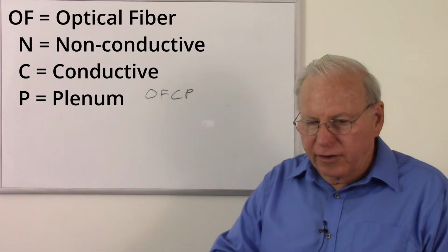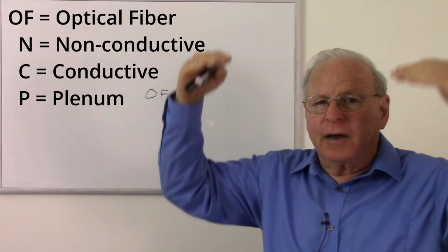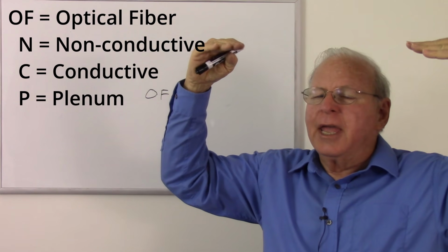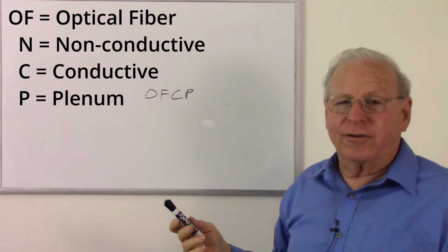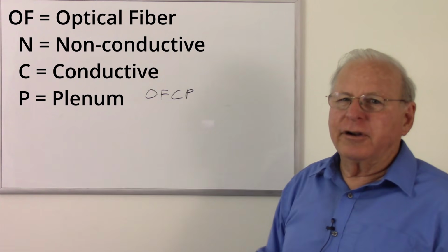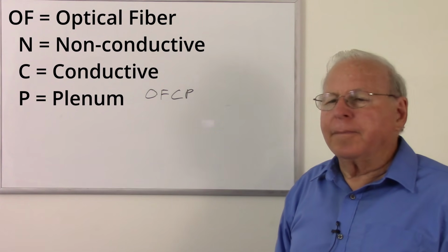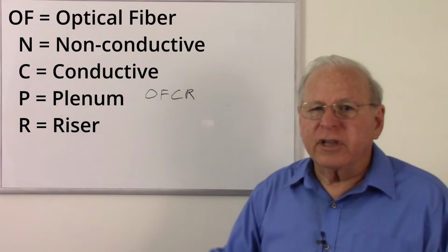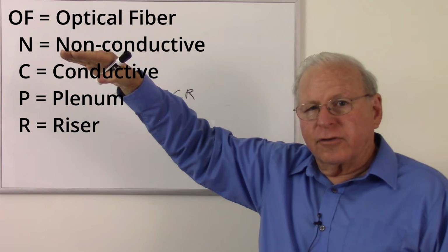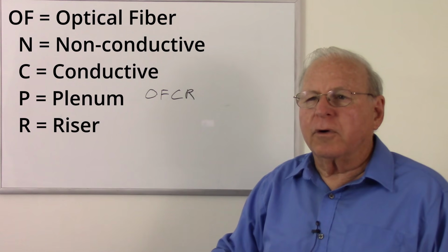And so under the floors where there might be ventilation, above false ceilings where there might be ventilation, and plenum cable, you can actually pull through your ventilation ducts. That's the best way to get your fiber from point A to B. Pull it through your ducts. You can do that with plenum cable. The other one, which is riser cable, you can use it inside walls if it's vertical, but you can't use it across false ceilings or below false floors.